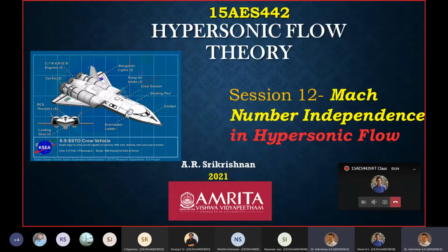many of the aerodynamic coefficients, when they are expressed as non-dimensional parameters, can be shown to be practically independent of Mach number in hypersonic flows. Which means that once you have some value for those coefficients, which you have got at say lower hypersonic velocities, you can approximate them to hold for even higher values of Mach numbers, because the expressions by themselves are Mach number independent. So that's what we mean by Mach number independence. We'll look at how we arrive at this conclusion.